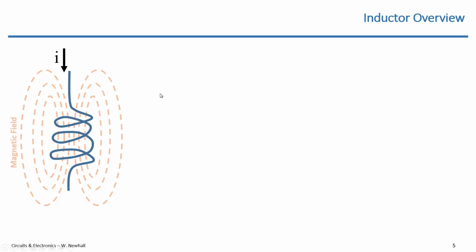So the schematic symbol of an inductor is this. It looks a lot like that coil. Let's define a current and a voltage across this inductor: current through the inductor, voltage across the inductor here. Okay. I think it's pretty intuitive that if you change the current through this wire, let's say from 1 amp to 2 amps to 3 amps, you're increasing this magnetic field strength, right? If you decrease the current through that wire, you're going to decrease that magnetic field, okay?